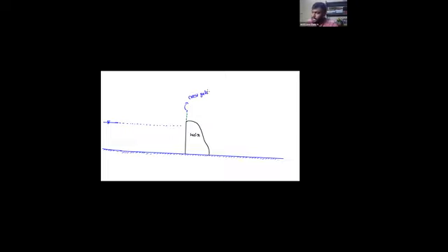Crest gate. So now, due to the obstruction, the water level is going to rise something like this. Yes. So once the water level rises, you tell me, do you think the change is going to happen only over here, or will it travel towards the upstream also? As long as I don't open the gate, the water level moves towards the upstream. And now this is the water level that I can see.